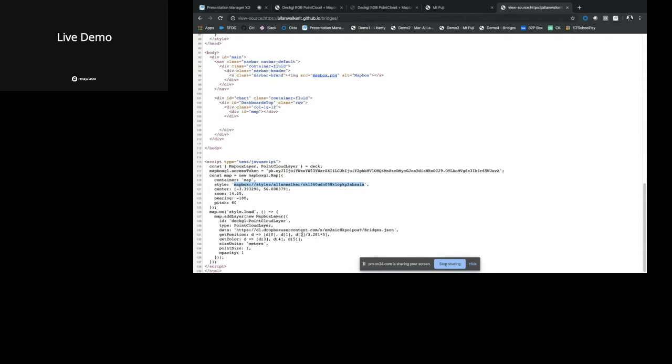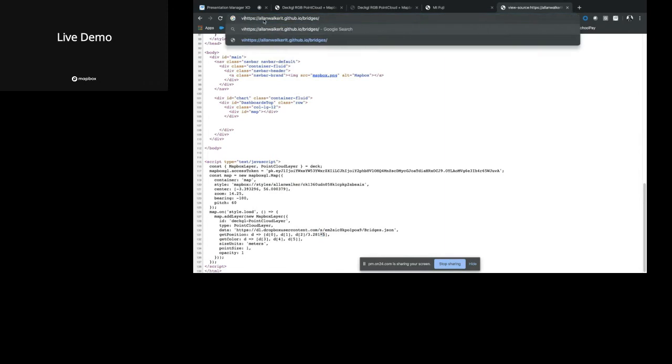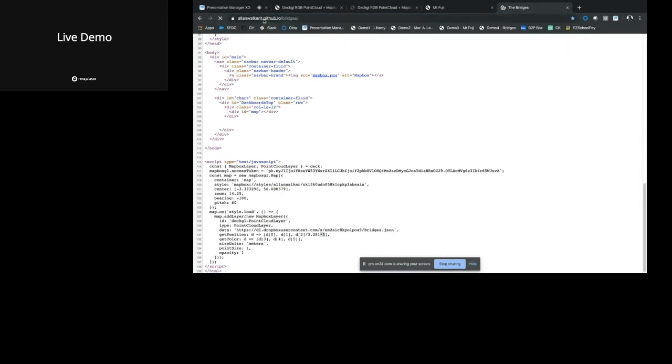The one thing that's definitely worth noting here, though, is that for the Scottish LIDAR, the Z values for the height are based in feet. So I do a simple calculation in here to convert the feet to meters. And then for the purposes of data visualization, I'm going to exaggerate that height by 5 times. So with that, my demonstrations are kind of complete.